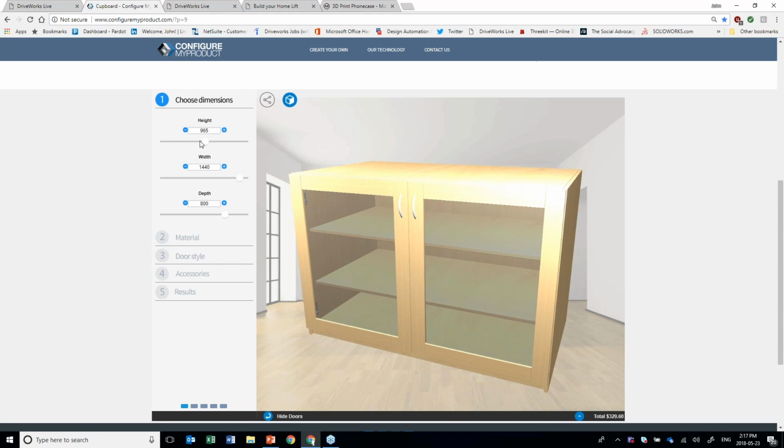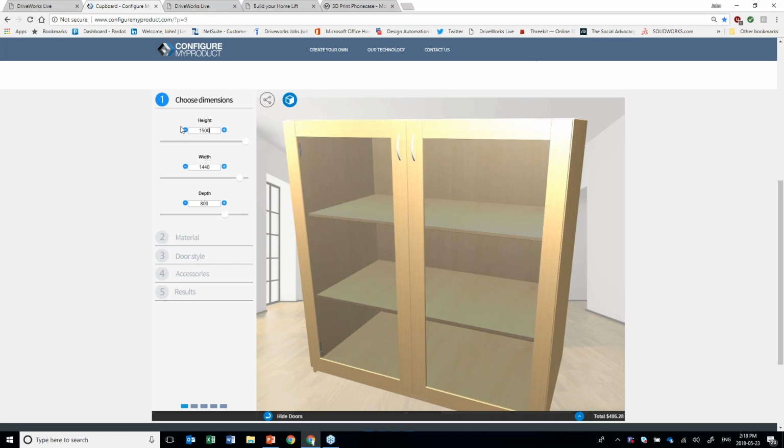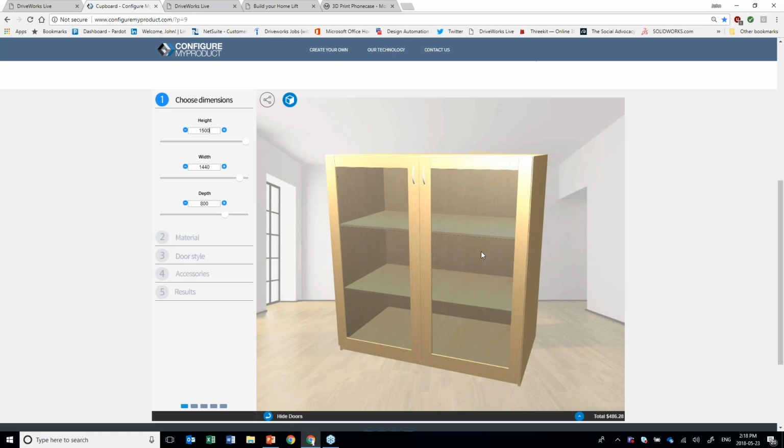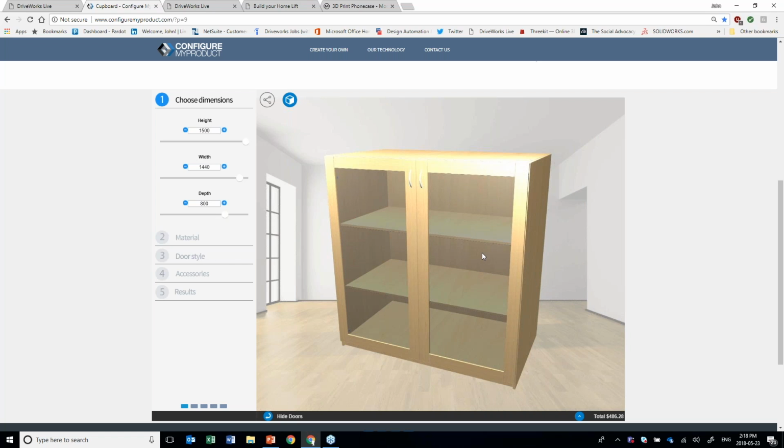Now these are totally flexible in terms of height, width, and depth. You can put in set sizes. If you have CNC equipment and you want to offer flexibility, you can do things like this. Just enter whatever number you want. Now the thing with this is you can't just add whatever number. So if I put in 75,000, that will max out at 1,500 because that would be a rule that you put in there because perhaps you can't manufacture greater than 1,500 in terms of the size, or maybe it's a material limitation or a machine limitation that prevents you from going any higher than that.